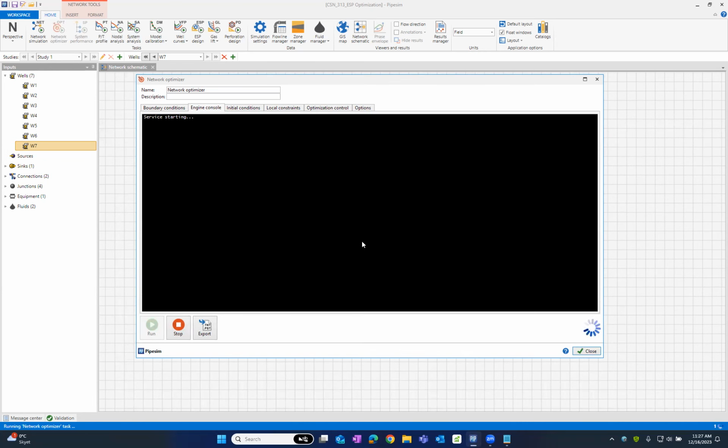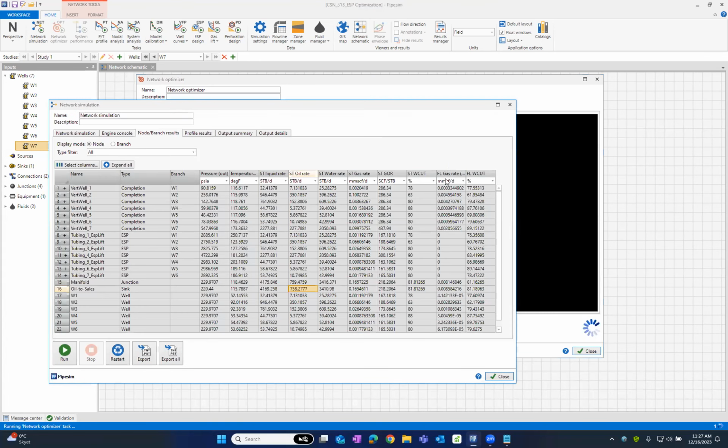the system is going to generate what we call well curves. Well curves represent the well response at different ESP frequencies, and then it's going to optimize. It's going to play with the ESP frequencies, but of course I gave it a harsh condition, which is that I don't want the water production to exceed 3,000. Although in reality, when all of the pumps are operating at 60 hertz, we're producing 3,400 barrels of water. And this was our initial oil production.